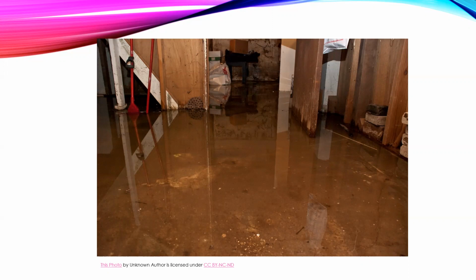It was far too low. It was more of a traditional basement, and the floodplain administrator didn't know that either, that there was a difference or that they weren't in the program. And so they approved it, and it was permitted, and it was 6 feet below ground and close to 8 feet below the base flood elevation. And so, yeah, that was a problem. And so some things like that might be why FEMA has put in a couple of warnings on the webpage and a couple places on both the non-residential and the residential floodproofing certificate, so that hopefully people will see that and catch it before they build something out of compliance.